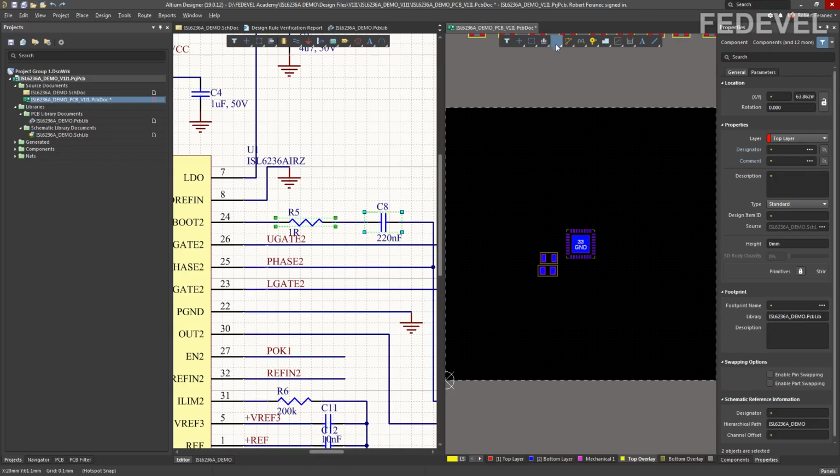Notice our reposition selected component command is now directly on this bar. Yeah? When you press right click, you can see this our command, it doesn't have any icon. And this bar which is here, it remembers the last command which we use from this list. So at this moment, the command which is here is reposition selected components. So you don't have to use the right click. You can directly press left click and place the components.